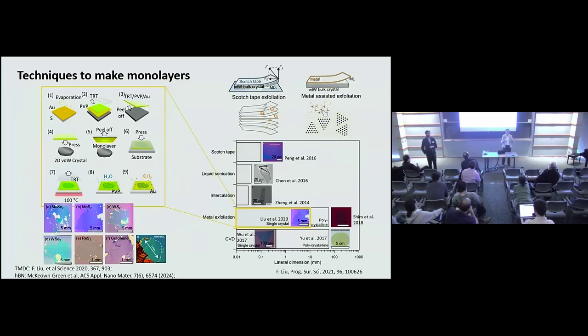Yes, we can. The challenge for that is we cannot find a large enough HBN. For a device, people usually use tens of nanometers thick HBN from exfoliation. Here, the HBN is 1 millimeter in size, but it is monolayer. This is not for devices. A device will need thicker HBN. Okay. Yes, this is too thin. There will be too much tunneling, and the device won't work, unfortunately.